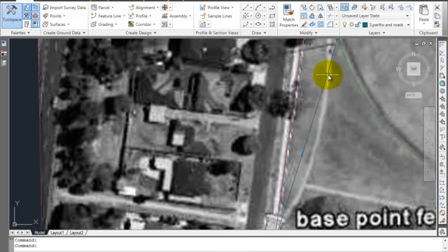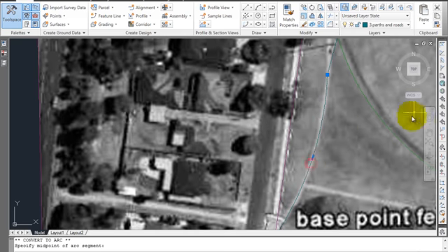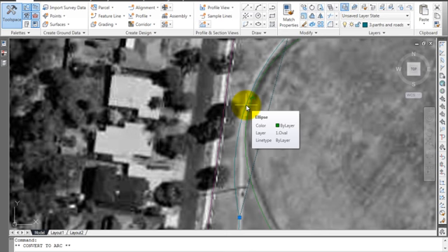And what I'm going to show you is when you mouse over it, you'll get the stretch, add vertex, and convert to arc. Now I'm going to convert to arc because I want to bend this line around just slightly to follow that line. Okay, and it's just a matter of pretty much guessing. And it's hard to see because I probably should have chosen a better colour. But you can see that it's not going to quite fit well.